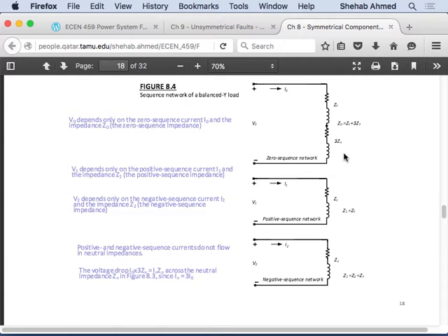Generator, you will be given those impedances, and sometimes you will be given more than one positive sequence impedance actually. This is important because the positive sequence impedance in the generator takes on several values depending on the value of current in the generator. At the inception of the fault, the current becomes very, very high, right?